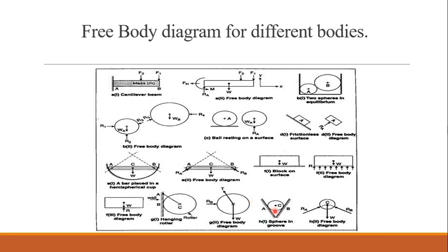So you can see the self weight will act downwards and there is a contact between the sphere and the wall here and here. So you will have a reaction here, that is in the perpendicular direction. So this is the reaction Ra on this component, self weight acting downwards, and this is the reaction which is going through the connection between the sphere and the wall B.